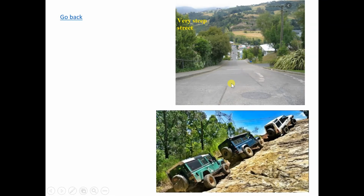But the thing is that for a steep road in winter there'll be a problem because the place can be very slippery. I think we have another guideline for places that have snow or maybe black ice. I think they limit it to 6%. But having said that, on certain roads, because of the development on both sides, you cannot cut down the slope. Certain places there'll be some exception.